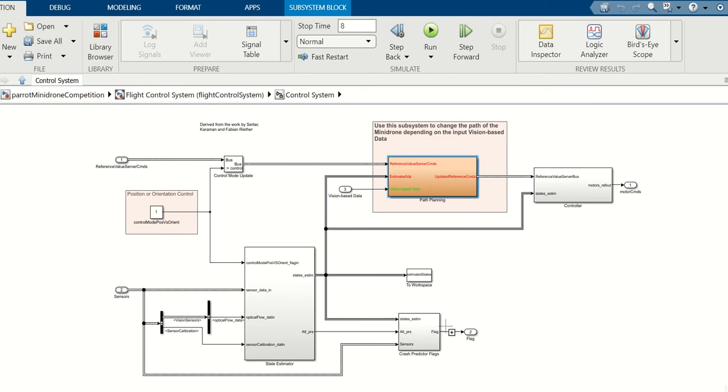Now in these set of boxes, the two that are interesting are this one here and this one here. Now this one we can use to change set points, and this one we can use to change controller gains. So when it says controller, that controls the controller gains, and this one can control set points in a simple way. It's easier to use than their signal builder.